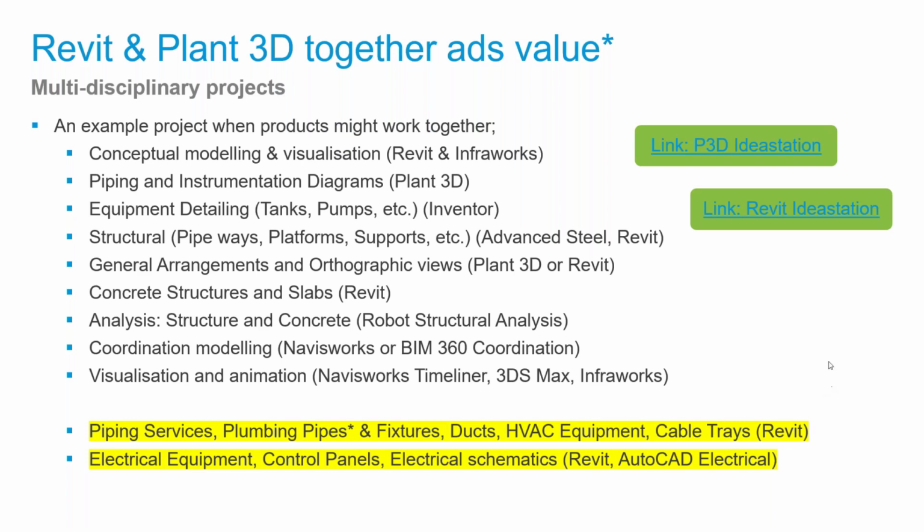I wrote an article, and the link will be coming with the Q&A, where after you generalize this path, you can also save your XREFs coming from the desktop connector into your model, and they will be available for the other users as well, just as a quick note here.